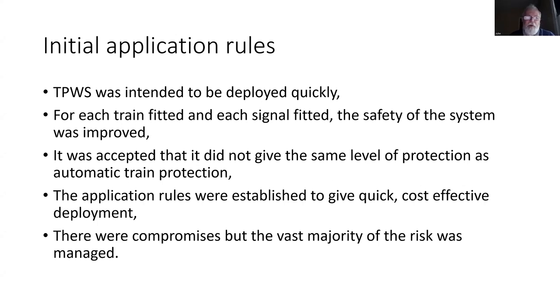So the system was developed and it had to be developed quickly and deployed quickly because the risk was out there, accidents were occurring. So TPWS was designed so that for each train fitted and each signal fitted, the safety of the system was incrementally improved. You did not have to wait for the whole fleet or the whole railway to be fitted, as we might need to do with ATP.